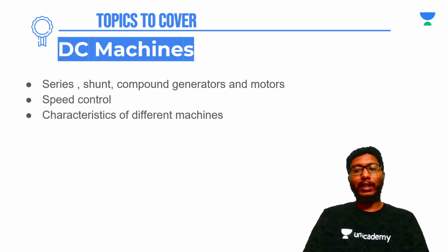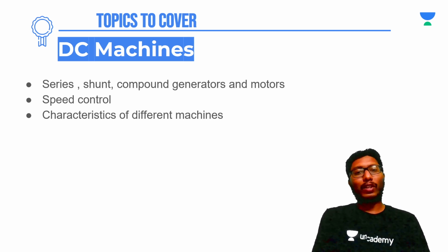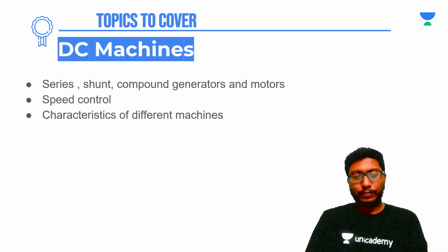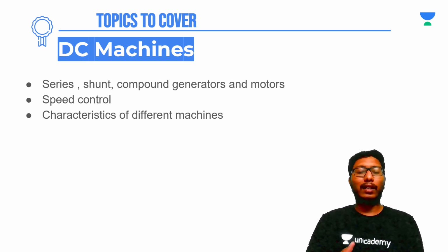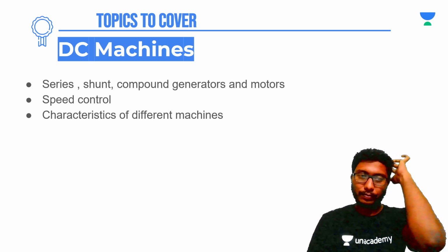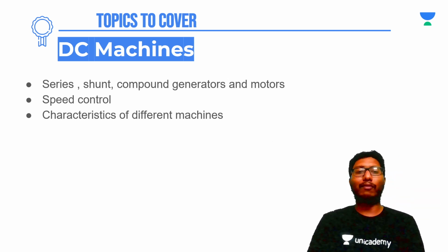So this is one more area where students are confused, that is while finding each of these parameters, flux and number of conductors. I am telling you once again. In order to find flux, you will be given a flux density in the examination, either 1 Tesla or some other number. And also you will be given the length of armature and radius of the armature. So you should just take 2 pi RL, that is the cross section area of the armature, and divide by the total number of poles, because what you are getting here is flux per pole.